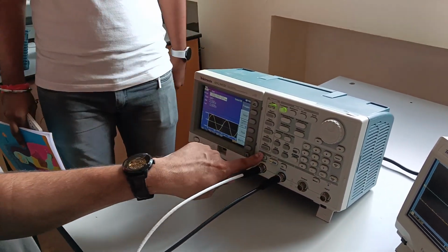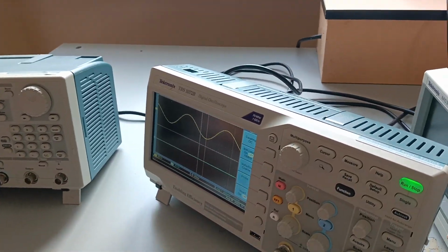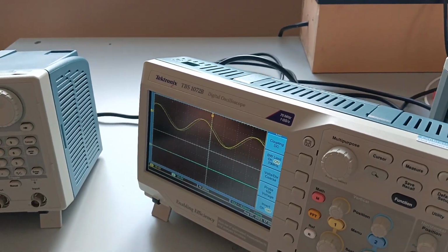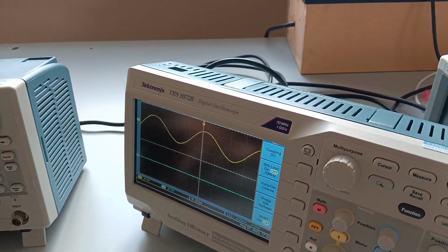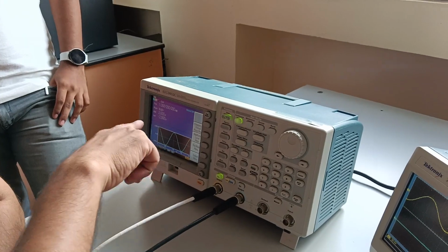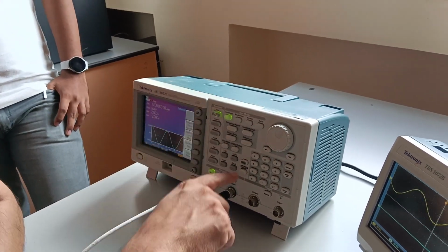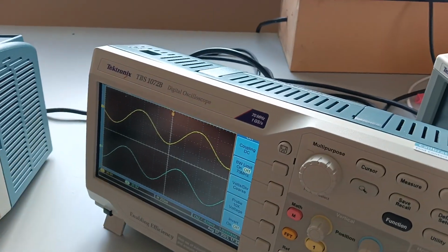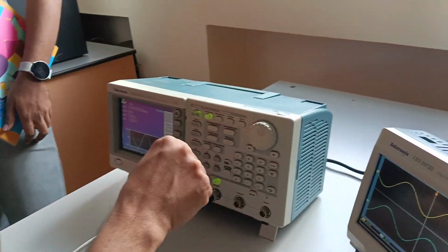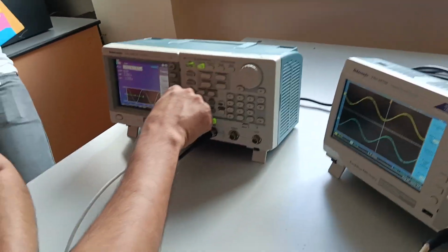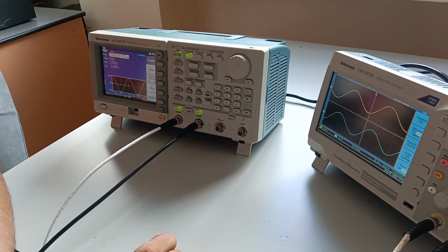Okay. And I give that out and I show you here. This is how it looks. Hardly surprising. Same thing I can do to channel number 2 with a frequency 1 kilohertz and the same amplitude, and you can see that okay, they are nice and aligned in frequency, time period, minimum, phase.